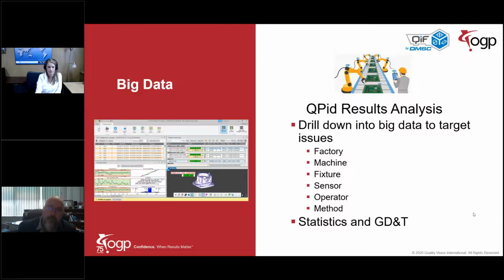Another thing I want to touch on was statistics in GD&T. When I'm taking lots of data on the same part, and you apply GD&T tolerances to it, I might have bonus tolerances. These tolerances become variable, and so having a good statistical package that understands that and can react and provide the correct feedback to the manufacturing tools, like Colby was showing, is important.